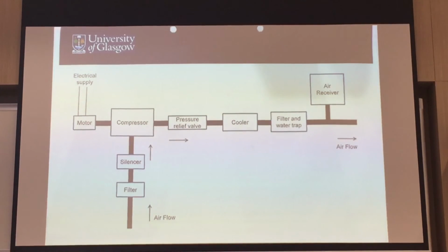So this air receiver will increase the volume of the air and correct small pressure fluctuation. So this, in a way, is like your accumulator. And once after all this, then you'll pass through your proportional valve, and then you'll go on to whatever actuation that's required. So this kind of like completes the entire signature.